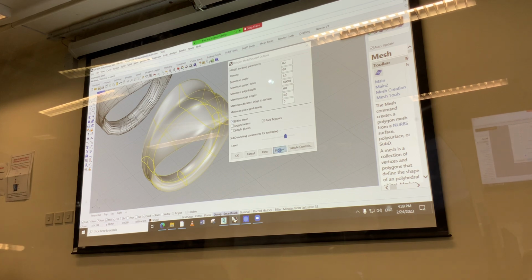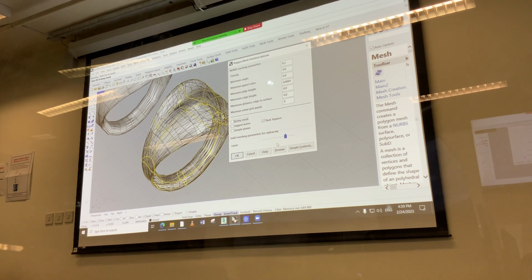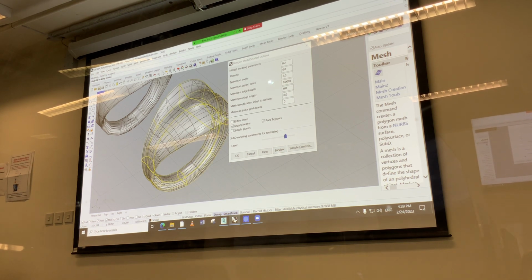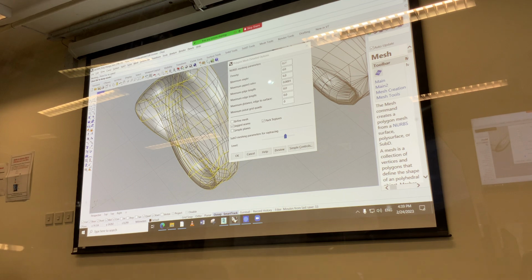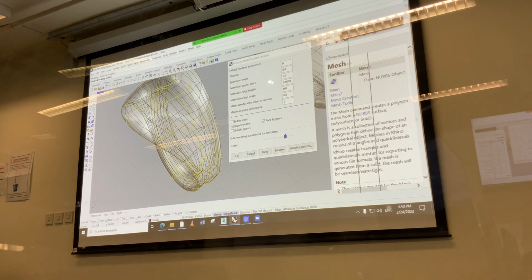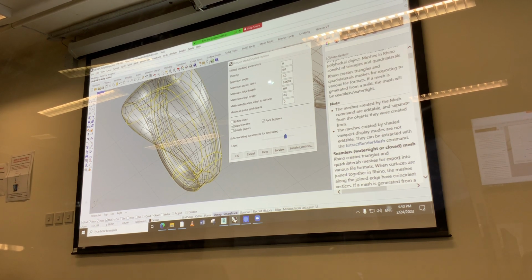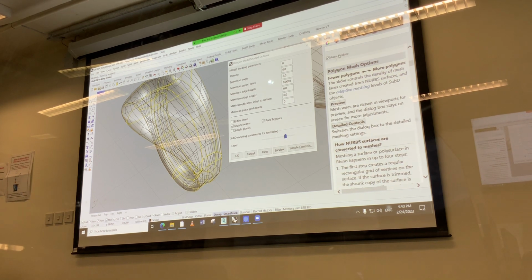So what happens, for instance, if I preview that? Okay, let's see, what is refining mesh doing? Nothing. Jagged seams. Oh, what happened here? Jagged seams gives me only quads. Now hello, that is interesting, right? So if we go a little bit higher, 0.5, by the way, you have as well the help on the side here that automatically tells you what you're doing, just so that you know. So here you have always a little help, which is on automatically.